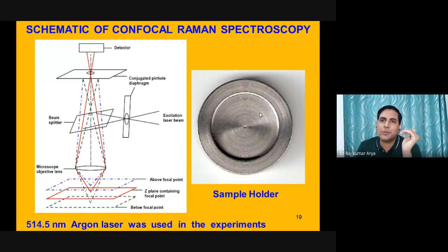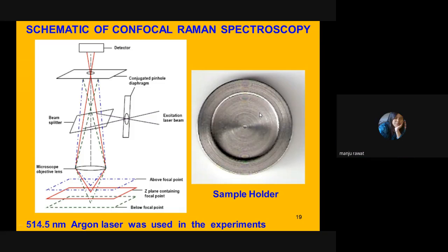So in the beginning, or maybe the time you clean it, the time you do the washing and cleaning, if you have just cleaned it with a very rough solvent, let's say tetrahydrofuran, tetrahydrofuran is the rough solvent. In that case, it will give very good etching resistance to this. And after that, if you apply the film, it will stick and won't come out that easily.